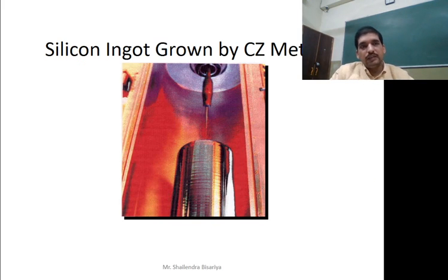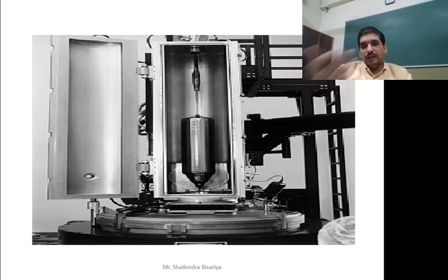So you have already seen this silicon ingot, which is finally grown, and then we can take it out from this puller mechanism. We can open the puller mechanism and cut the upper portion, the seed crystal, and take it out for further processing. That means for slicing it and forming the silicon wafers. Okay, so this is the Czochralski crystal process, which tells us how a single crystal structure can be obtained from multi-crystalline, that means polycrystalline EGS.